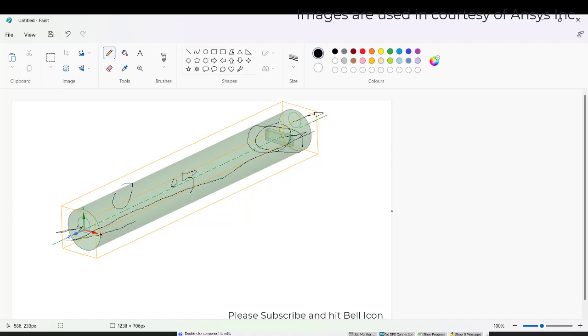Maybe we can take a volume fraction of 0.5 for the water, and we'll see how the isosurface is moving, and all the pressure contours and velocity contours. We can check all of this in Ansys Fluent itself.